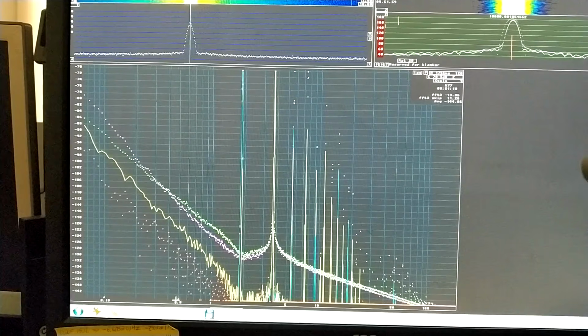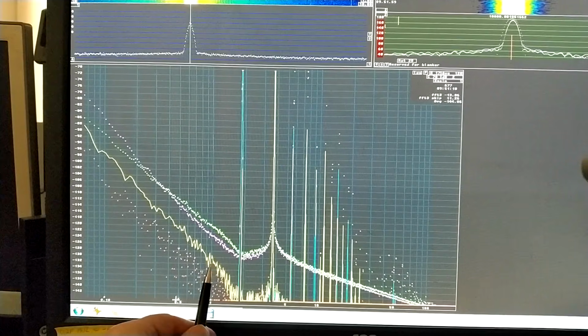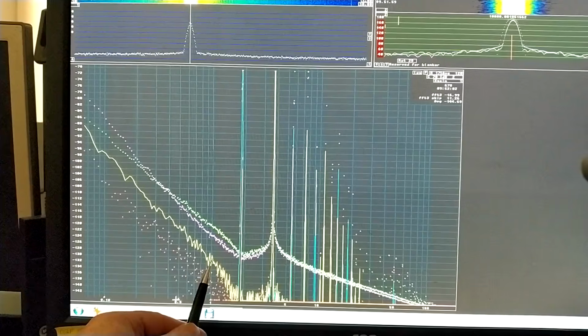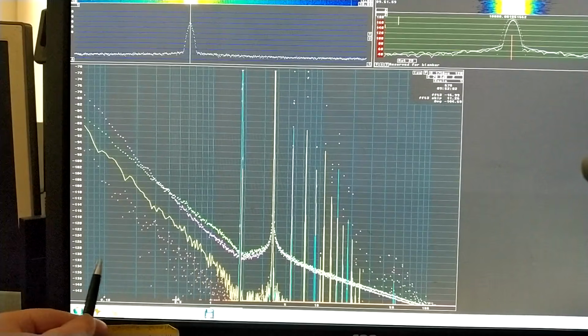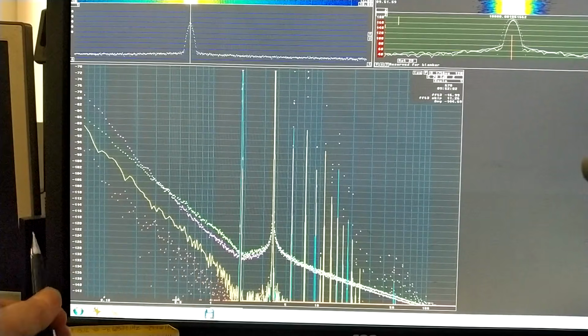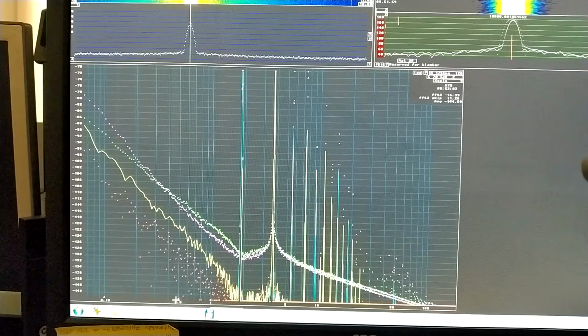When I look at the Linrad phase noise screen, at 1 Hz I see this from here, 131. So it's not quite as bad. This could be because Linrad has an algorithm that detects interference pulses and excludes some sequence of data when such things happen.